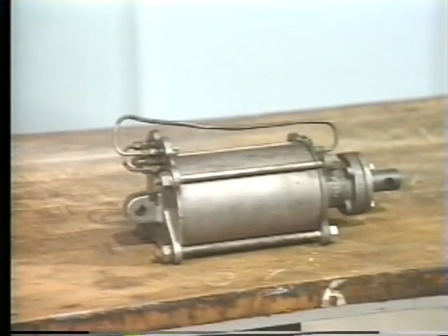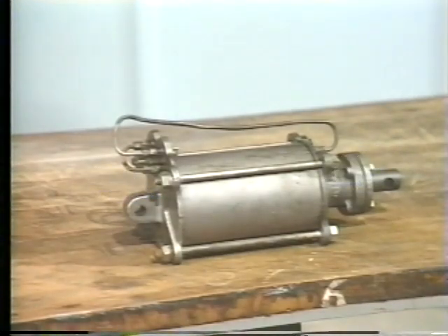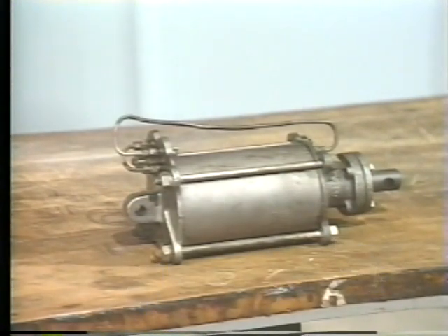The main body of the piston actuator consists of a hollow rigid metal tube or cylinder and two end caps. The cylinder and end caps are connected by 4 long bolts that are threaded on both ends. Nuts are screwed on to the threaded bolts to hold the whole assembly together. This end cap has an anchor point that is used to fasten the actuator to a solid stationary object. This allows the entire actuator to pivot with the movement of the linkage without binding. The end cap also has an air port that allows air to enter or exit the cylinder.